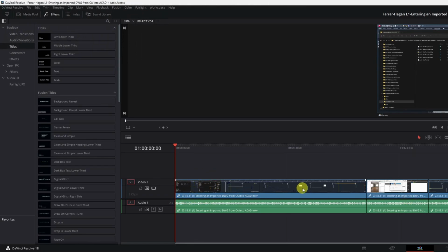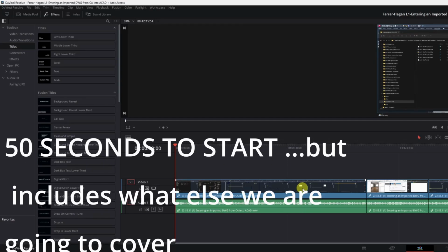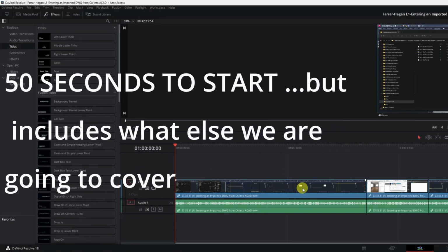file from AutoCAD. And if you saw lesson 0, I called it 0 because it's more of an error issue I was getting, but it does also show how to resolve it if you happen to get that error trying to export a DWG from Chief Architect and then Xref it into AutoCAD. If you get an error, it shows you how to get around that.